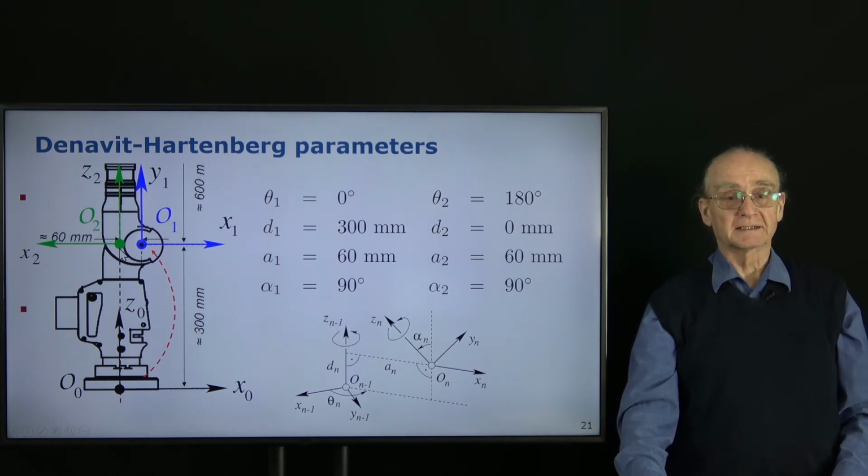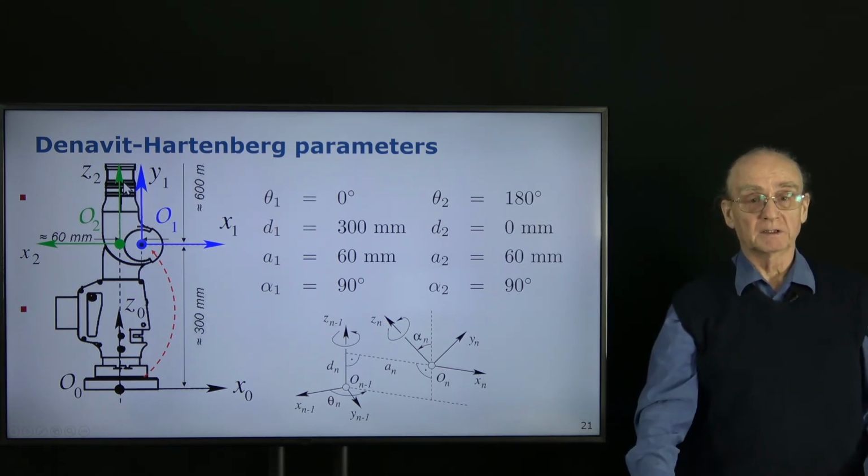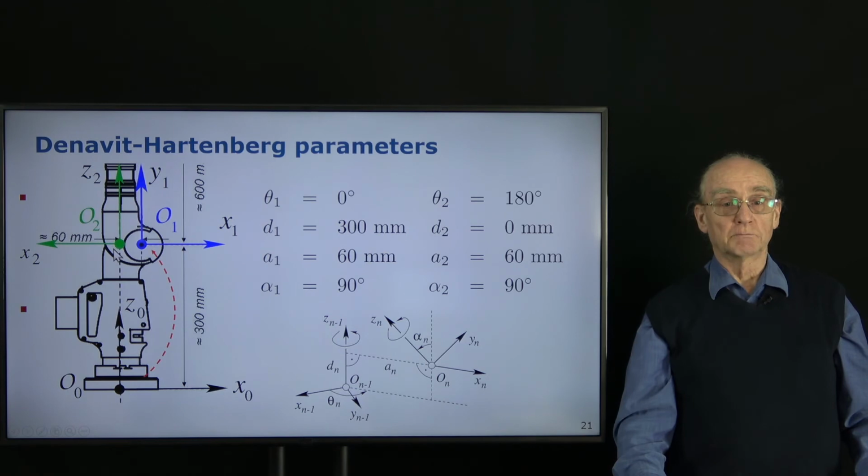Now we go to the second axis. Now we have a rotation again in the vertical direction. That means actually the z0 and the z2 axis are the same line in 3D. So the origin of this second system will be at this green point. So these 2 points are actually those points which are sitting on the line closest to both lines. So this is the origin.